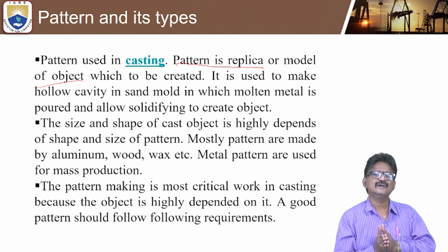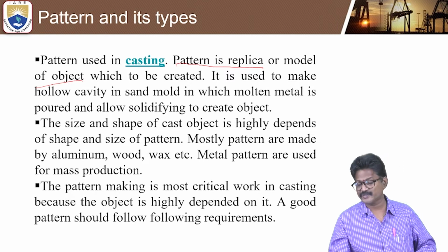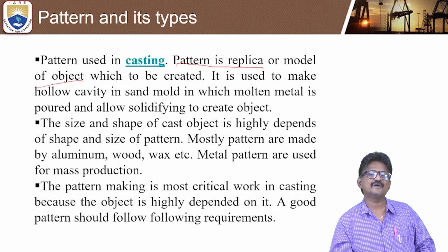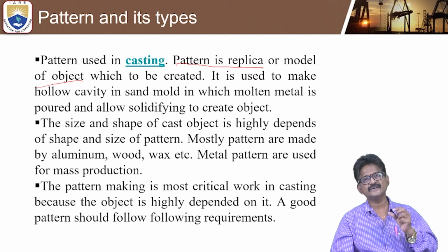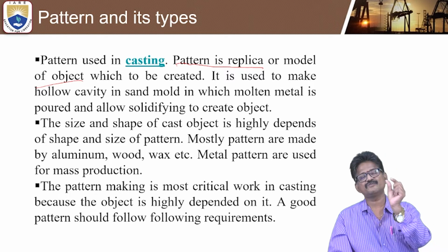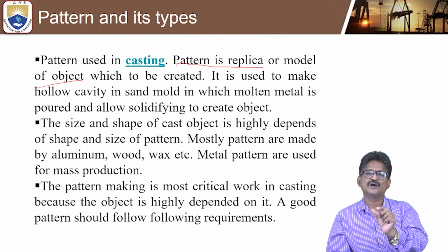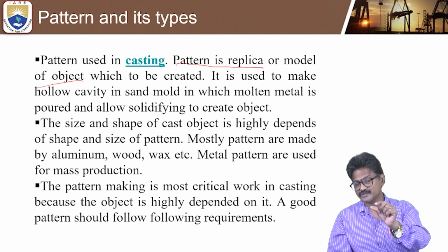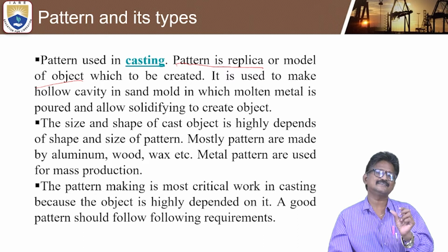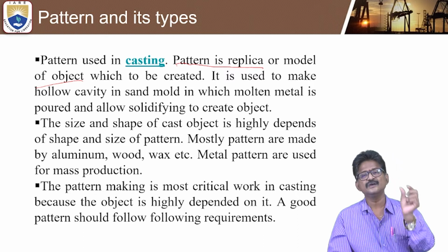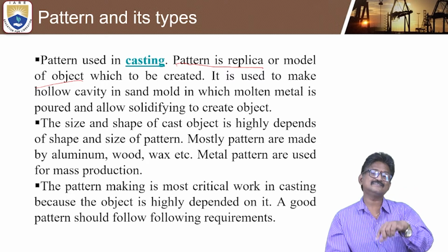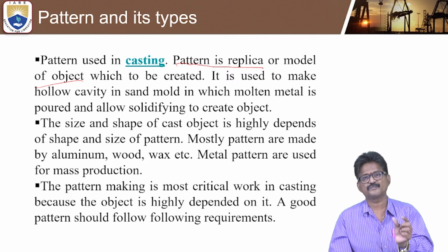Some plastic patterns are also available, and ceramic types of patterns are also available. Before selecting the pattern, first of all, what type of application you are choosing, and how many components you are going to produce, these things should be kept under consideration. Only then should you select the pattern, what material, and what are the advantages and limitations of the particular pattern.